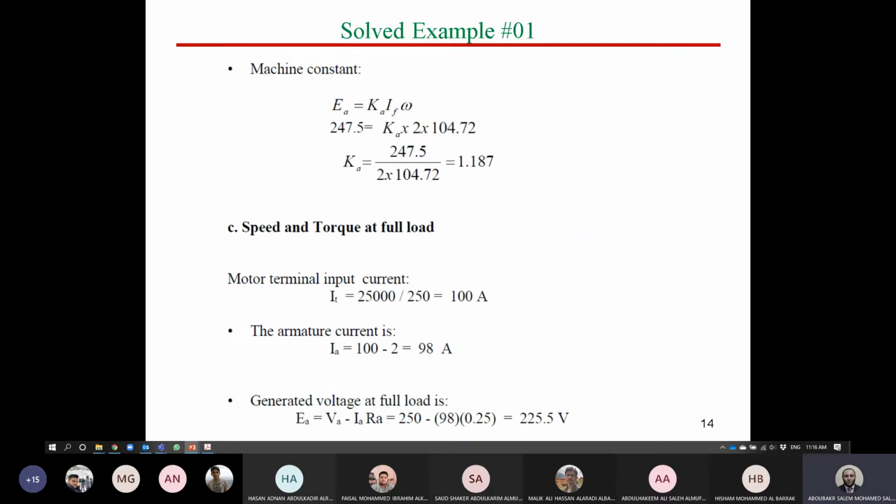So, as we discussed, we can now substitute in the equation EA equals K, which is the motor constant, multiplied by omega, okay, and get the value of K. If you would like to get the exact value of Ka as a function of IF as well, it's possible, because here we have a branch for the field current in the circuit. So if the field current is going to be changed, we have to consider the motor constant as Ka, not the overall Km.